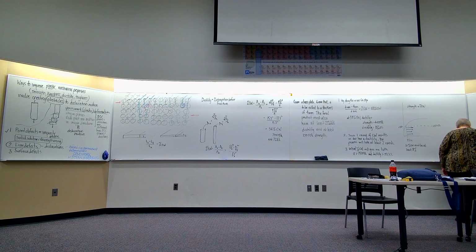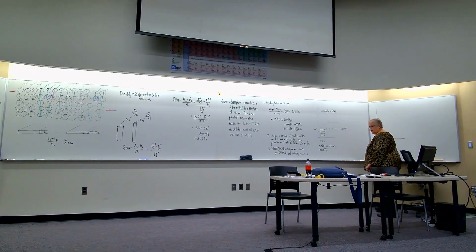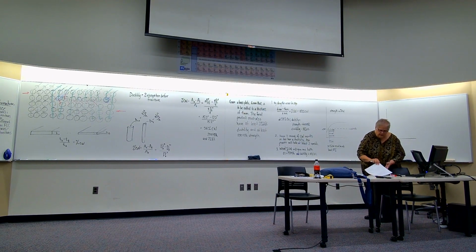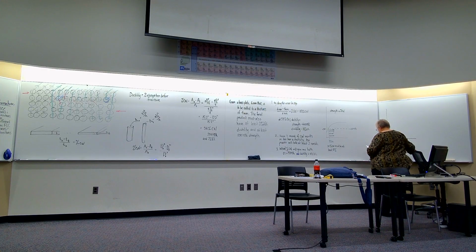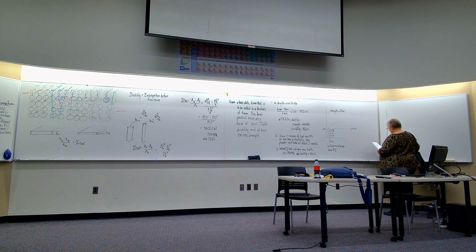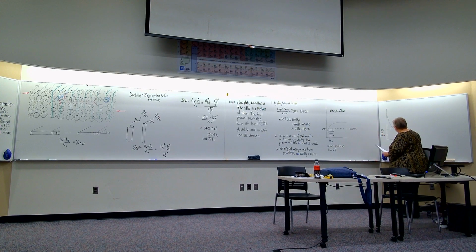All right, now if I look at ductility versus percent cold work for brass, it kind of looks like that. And I want 20. It's about there.